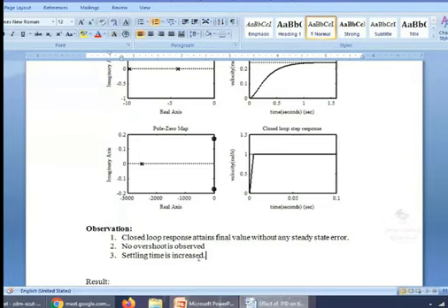See, let me narrate the drawbacks of the controllers sequentially. Proportional means it will reduce the steady state error, but still there is a large steady state error possibility. Then proportional plus integral means steady state error will be reduced, but there is an overshoot. And if I am introducing proportional plus integral plus derivative, my overshoot is nullified, but the problem is there is a slight time delay in order to reach the settling time.